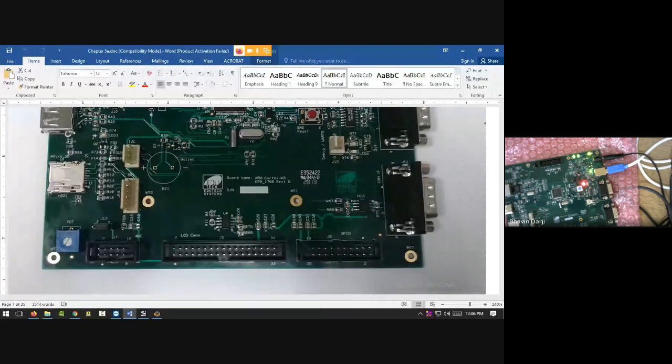So this kit supports different peripherals, different protocols. There are LCDs available in the market which use I2C and SPI interfacing protocol. So using this protocol, we have created some examples using which we can interface a touchscreen LCD on this connector. So this is the 34-pin LCD connector, and on the left side there is an ADC connector.